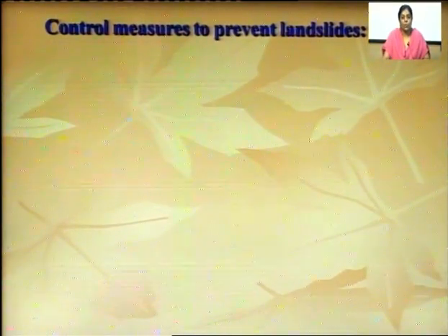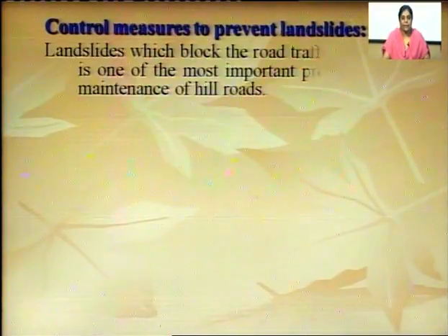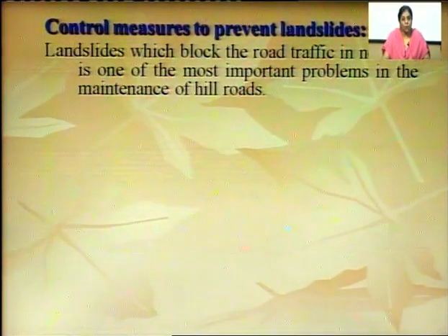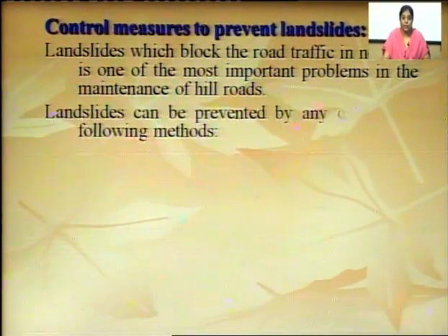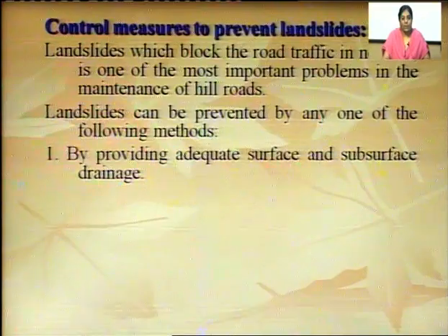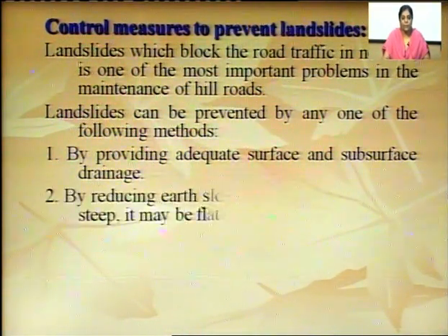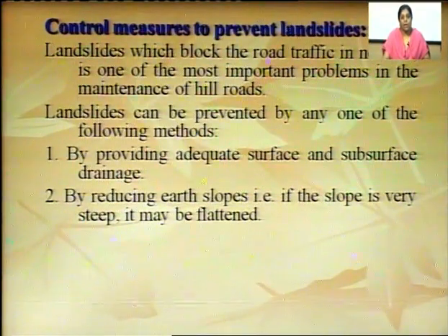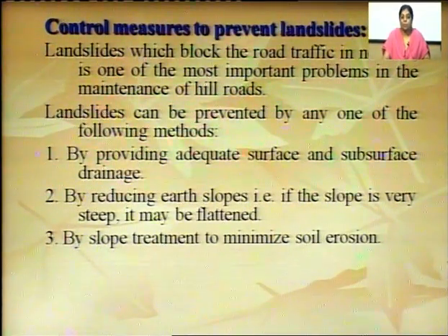So, what are the control measures to prevent landslides? Landslides which block the road traffic in no time are one of the most important problems in the maintenance of hill roads. So, landslides can be prevented by any one of the following methods: by providing adequate surface and subsurface drainage, by reducing earth slopes, that is, if the slope is very steep, it may be flattened,